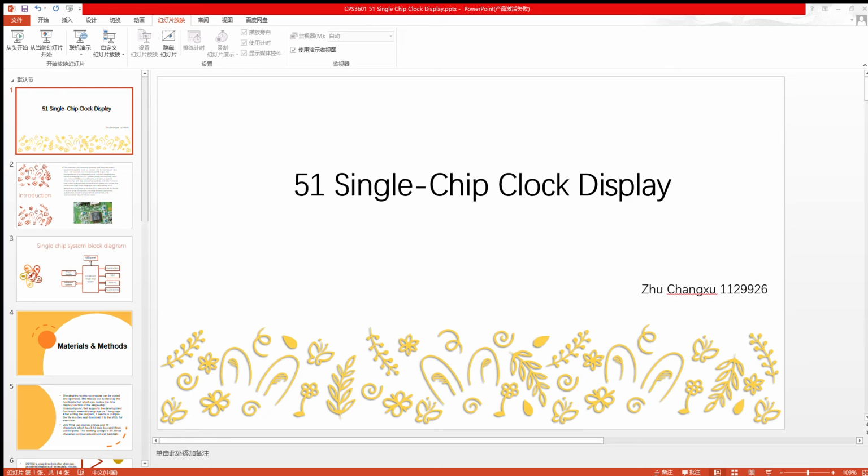The whole development includes 4 modules. The LCD module includes display string, display decimal number, and other functions. The time generation module generates time information through the DS1302 real-time clock chip and can write and read the time information into the DS1302. The data storage module uses a memory chip to save data.